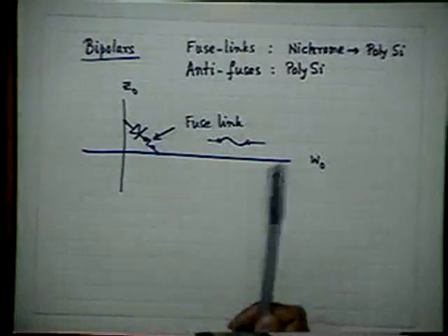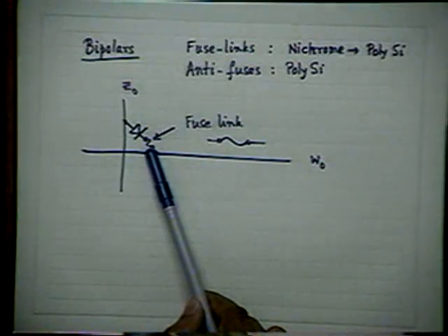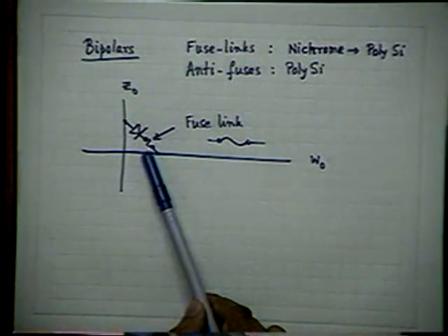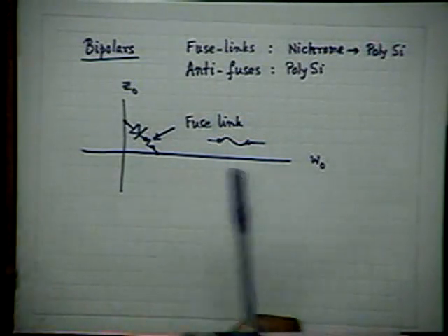And the current will flow over current, and if the current is above the so-called fusing current, as you know, 3 ampere fuse, 5 ampere fuse, but one cannot have 3 ampere fuse here. The fuses must operate at current levels less than ampere. Usually in early days, it was typical to have fuses operating around 500 milliampere current, particularly in the days of nichrome fuses. Nichrome fuses, very thin nichrome films in the form of resistors. These are nothing but nichrome resistors, but nichrome is the material used for making thin film resistors.